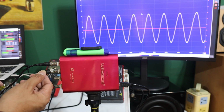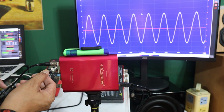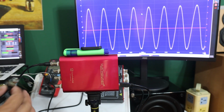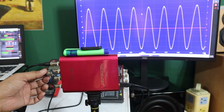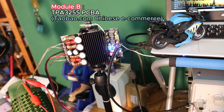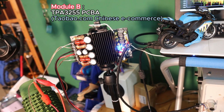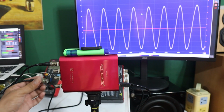That is the problem. It reduced from 2.8 to about 1.9 volts, and that is a problem. I suspected initially that the board, the module B that I'm testing, the TPA3255, has a problem, but eventually it's not.